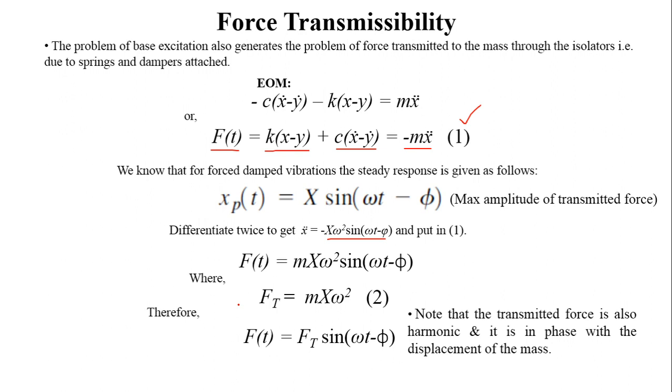So this means that the transmitted force, the dynamic force that is being transmitted to the inertia element because of the motion of the base or the support via the vibration isolators, that is the spring and damper, is given by the last expression on this screen.